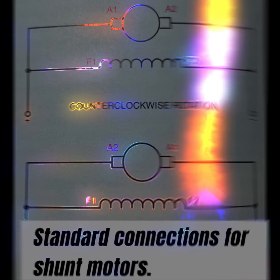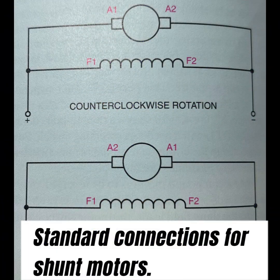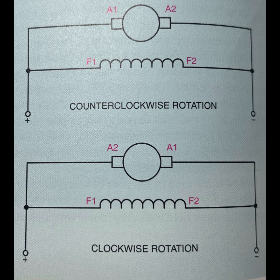When the direction of rotation of a series or shunt motor is to be changed, either the field or the armature leads can be reversed. Many small DC shunt motors are reversed by reversing the connection of the shunt field leads.